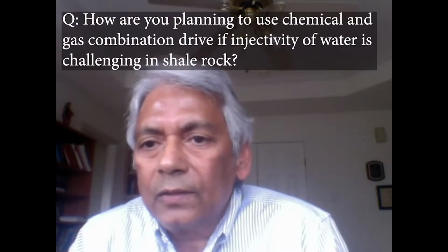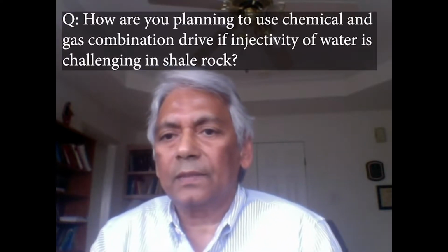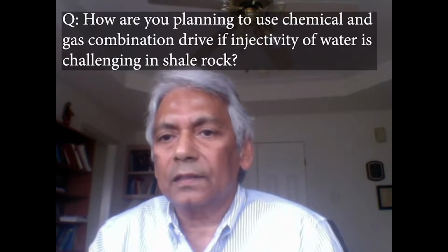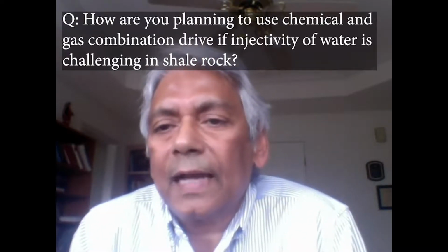How are you planning to use a chemical and gas combination if injectivity of water is challenging in shale rock? Yes, so what we are thinking right now is you should inject, let's say, CO2 or some other gas to a pressure of, let's say, 2000 psi. And then you inject the chemicals to push the CO2 in. So CO2 would actually physically go into these matrices.